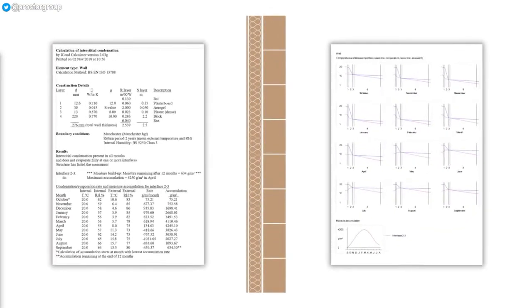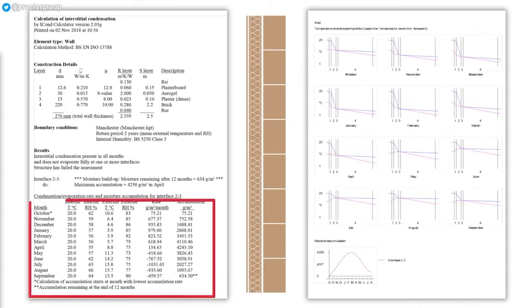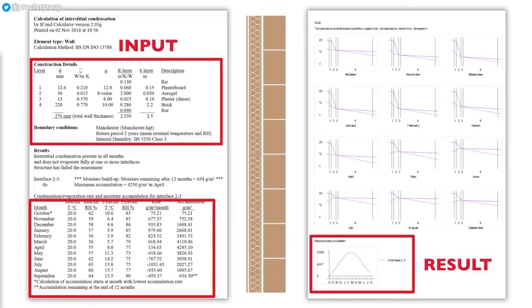Both standards rely on a calculation method known as the Glaser method, which was developed in 1958. Glaser uses steady-state heat conduction along with average monthly temperatures and the vapour pressures to identify vapour diffusion and model how vapour passes through the building fabric. This gives a reasonable assessment with a comparatively simple process and simplifies data input requirements.